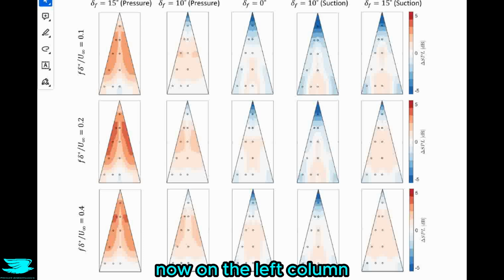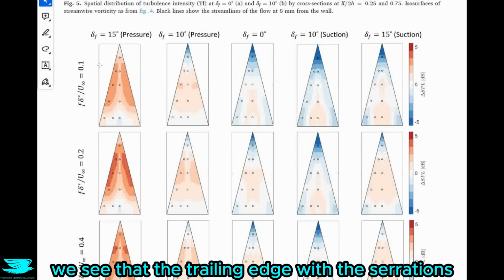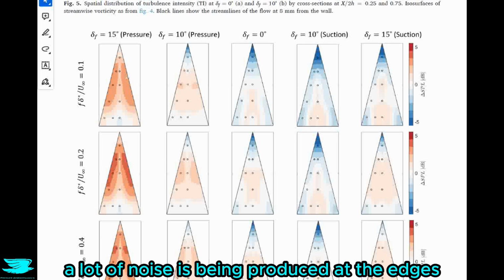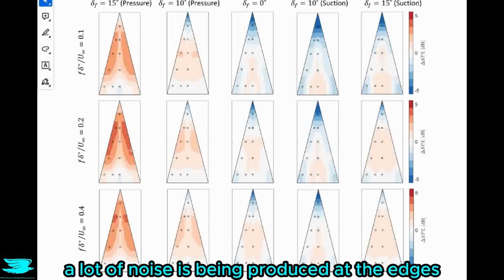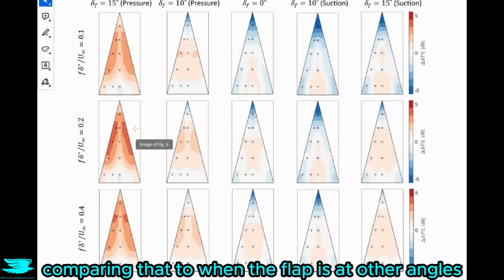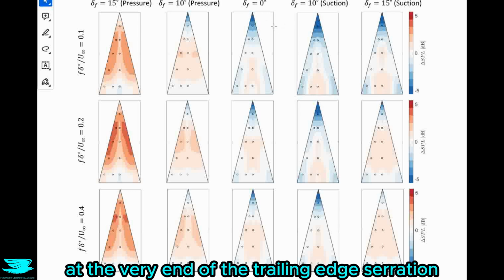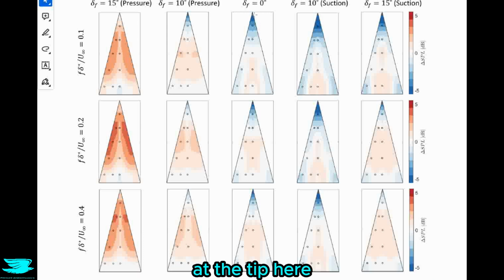On the left column, we see that the trailing edge with the serrations, when the flap is deflected at 15 degrees, a lot of noise is being produced at the edges here in this red. Comparing that to when the flap is at other angles, we don't get nearly as much noise being produced here. In fact, at 0 degrees, we even see quite a big drop at the very end of the trailing edge serration, at the tip here.